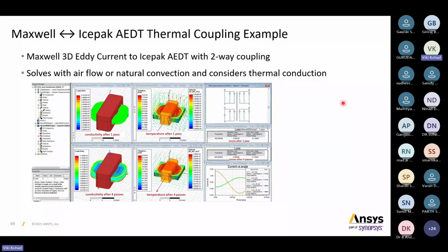If your temperature goes beyond 22 degrees, your conductivity value decreases by 0.37%, as the temperature goes above 22 degrees Celsius. So this is basically the data sheet formulas, or you can say the data sheet values we have to find out to calculate the temperature part accurately. At which point the conductivity decreases, at which point the conductivity increases, is based upon the temperature.